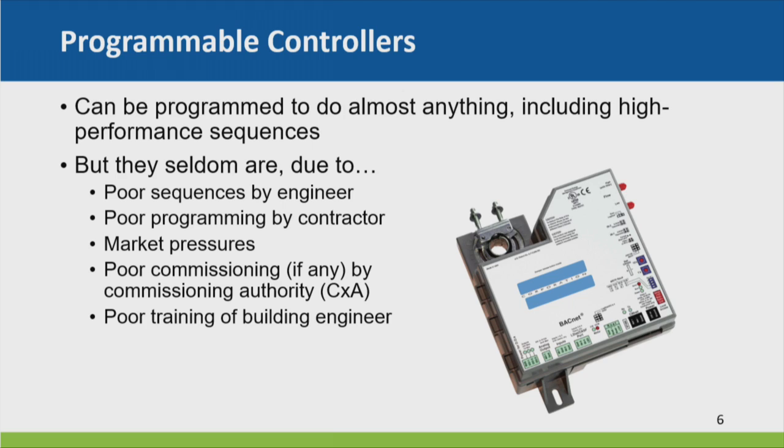And often we get poor programming by the contractor. We have market pressures to get off the job. And I heard in the bios, a couple people used to work for a controls tech. Who's the last guy on the job, right? It's a controls person, and they're often a sub to the mechanical, and the mechanical is beating them on the head, saying, "You're done, come on, I want to get paid." And they often have to sort of leave early when they're not really done, just to make everybody happy. And they're often poorly commissioned or not commissioned at all.